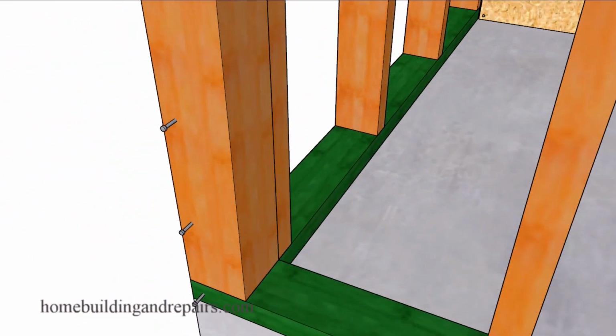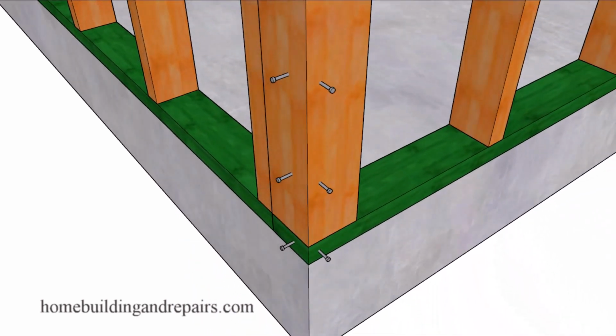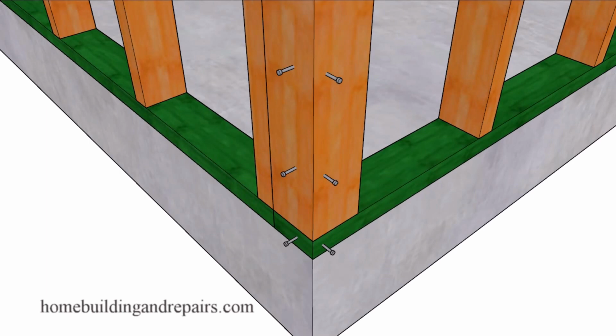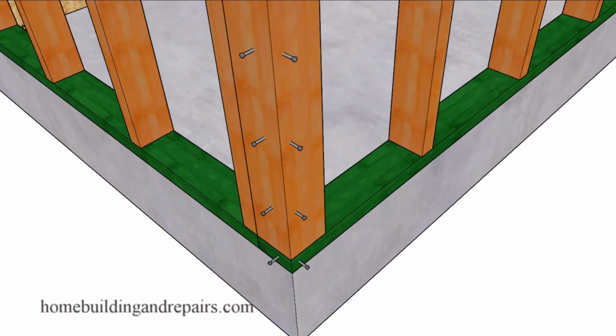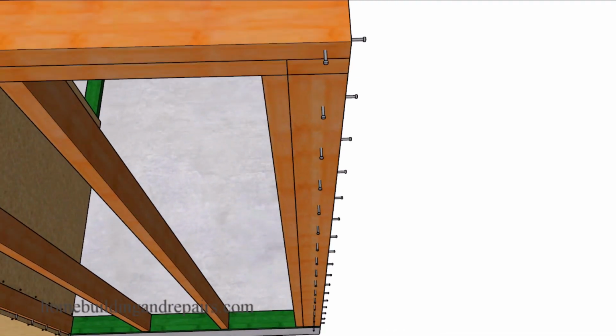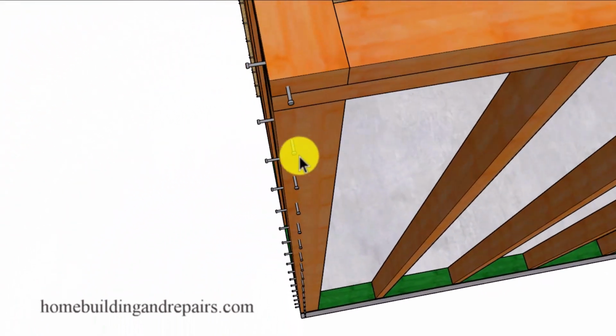Now, if we're looking for something a little stronger, we can install a 4x4 post or even a 4x6 post. And a 4x6 post would be helpful if you have shear panel going on the inside and you're not planning on moving this framing stud over to run the shear panel through. And since we have a 4x4 here, we're going to be able to put more nails in it, or at the very least create an area that might not allow the lumber to split as easy.